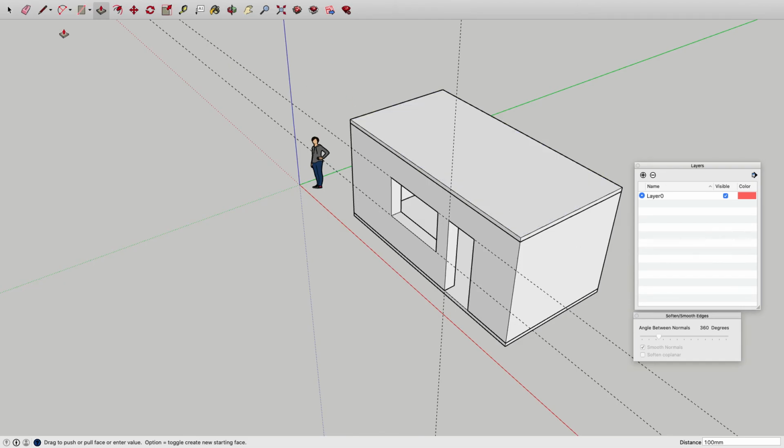Check this out. I'm going to go over to the pen tool. And I'm going to hover over this line in the back. And you watch as I hover over, it's red, red, red, red, red, and blue. That is the midpoint. I'm going to click on the midpoint, drag across. You see that it's locking in as a red because it's parallel. Yes. And click on the other side on the midpoint. Pretty cool.